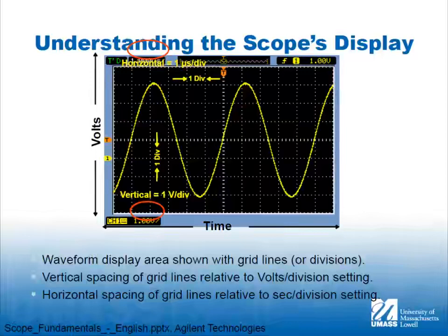Okay. The other axis, the horizontal axis, is time. Now, time is very important to us. And here we're getting an illusion that the time is continuous, that I can measure between any of these 2 points. But you can see there's some staircase pattern, some quantization of the signal. So it's still sampled, but it's sampled at such a high rate that at 1 microsecond per division, this distance is 1 microsecond, it's a lot of samples.